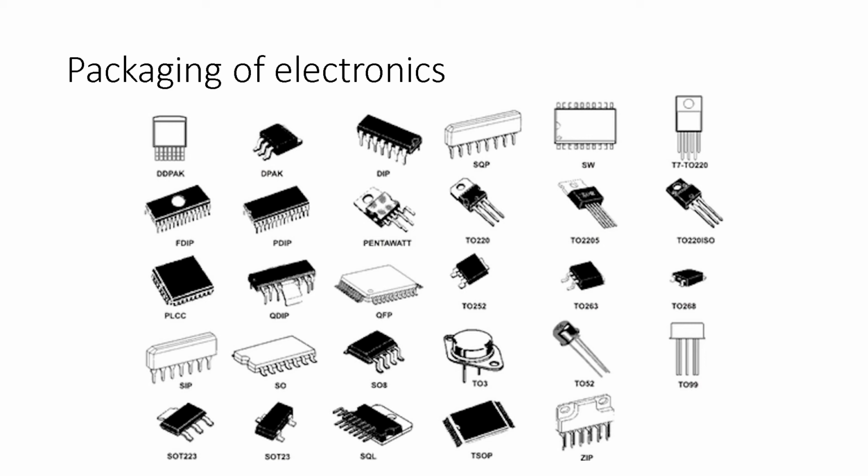Some of the most used that we're going to use in class that you're going to see are DIPs, dual inline packaging. We have PDIPs, we'll see those a bit, TO-220s. Essentially, there's many more than this, but this is a nice little selection of the most commonly seen ones. So some of these are through-hole mounts, and those through-hole ones have little legs that go down through the circuit board, as opposed to surface mount ones, which the legs stick on the top of the surface board.